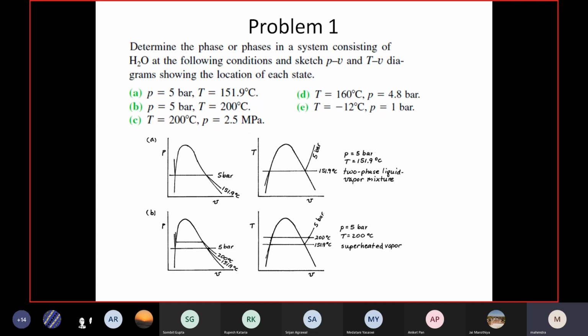Later on you need not worry about how to see the steam table, how to use the formulas, how to calculate. So please go to the table at 5 bar. What is the saturation temperature? Please let me know. Since our working substance is H2O, go to tables A2 and A3.